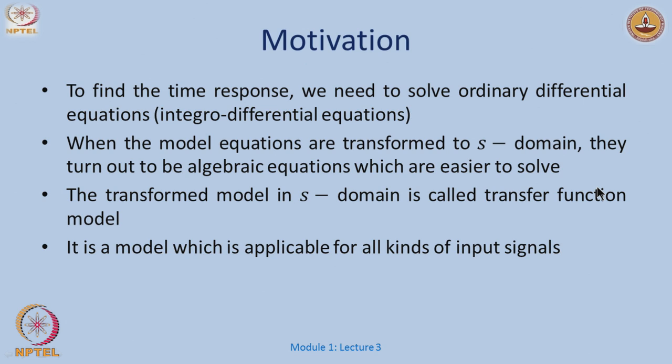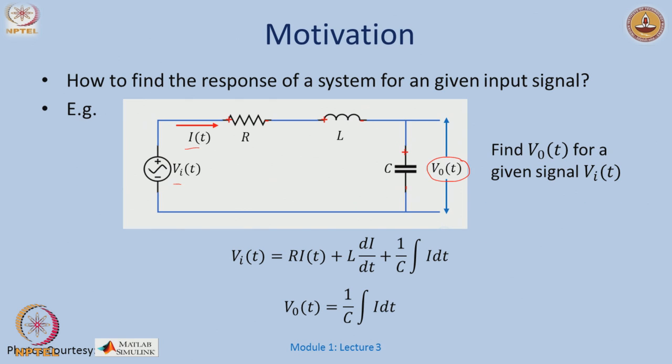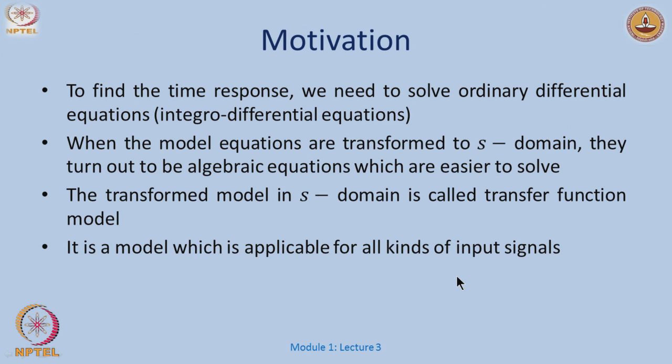Okay. So, what does this mean? To find the time response, or how V_o changes with a given V_i, we need to solve a certain set of differential equations, ordinary differential equations, or even sometimes integro-differential equations. You see the little integral term over here. What we also saw earlier is that when I transform my differential equations into the Laplace domain, or the s domain, the differential equations turn out to be simple algebraic equations, which are then easier to solve. Linear equations are usually easier to solve than differential equations, right.